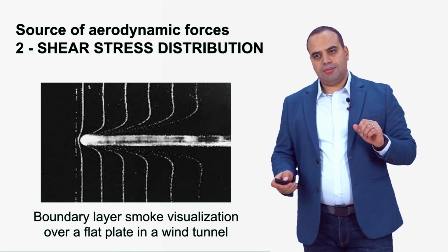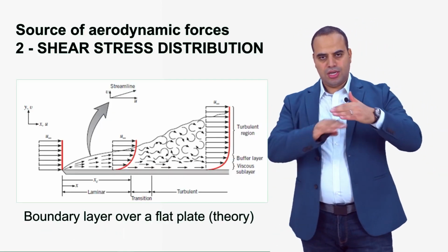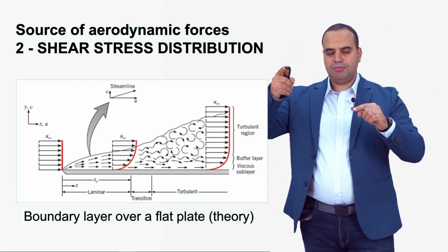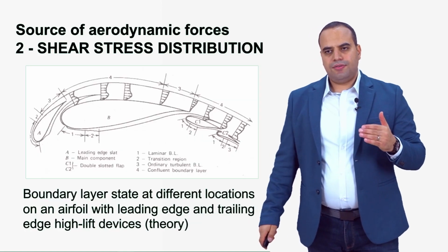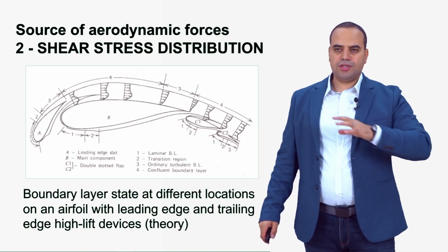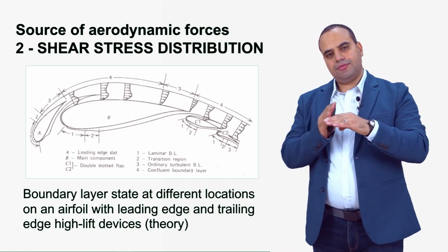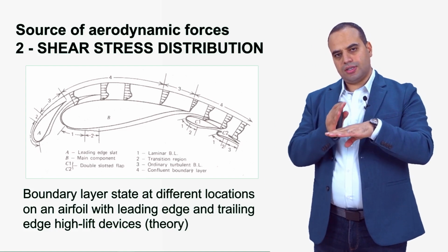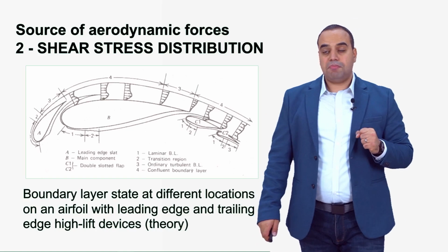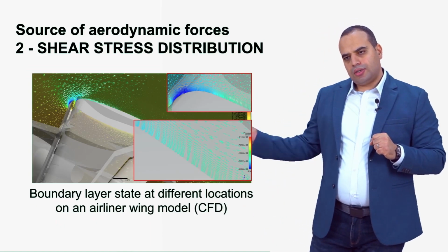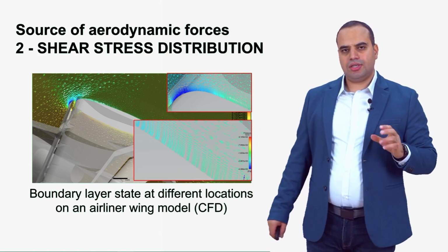So you can see, for example, in the beginning it's a little bit like here, right? This is called the laminar boundary layer. It is just a very simple relationship where the velocity increases the farther away we move from the surface. If we move to certain other locations on the airfoil, we can see that relationship is a little bit changed, where the gas completely stops on the surface, and the picture of the boundary layer changes, and this impacts the friction drag, right?